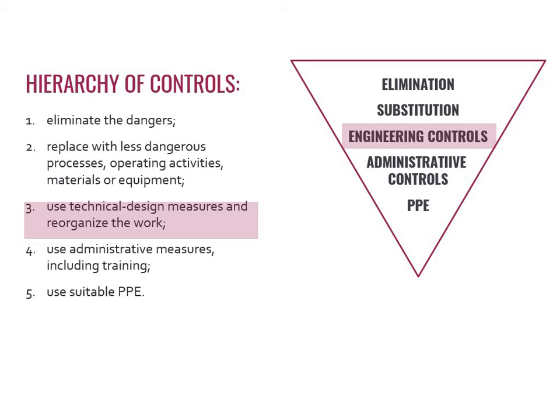So, let's move to step 3, engineering controls. A good way to eliminate hazards could be changing the factory layout. Maybe most of the work could be done in another area in which the noise level is significantly lower. Only after we tried to eliminate the hazard, then we could go through the path of risk reduction. This could be achieved through implementing protective measures, such as insulating the machinery, or providing and ensuring the use of personal protective equipment, such as ear protection.